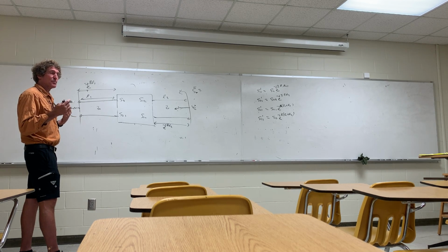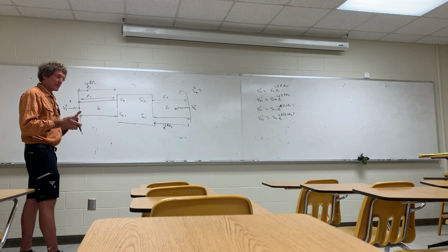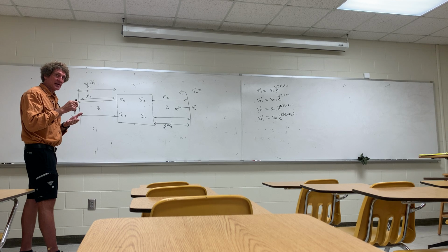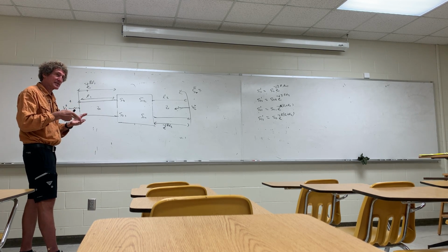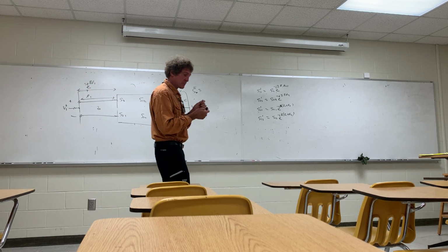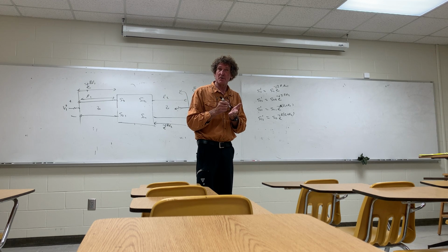Now, the reason that's important is a lot of times when you're investigating electronic stuff, this is only for 3 layers, but it could be for n layers, you don't really know what actually happened to the material when you did device processing. And the minute you start going in and doing destructive engineering, you can actually change the properties in doing so. In other words, if you start slicing the thing up and you want to take it for a scanning electron microscope graph or something like this, then you can destroy what was actually there. So you don't know what's there.